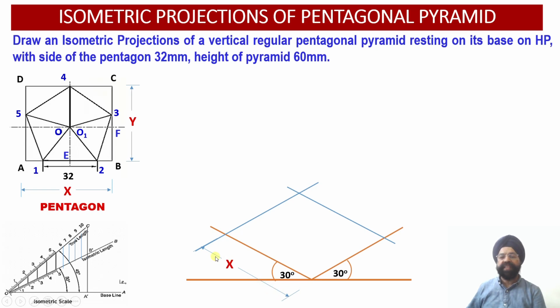By drawing the larger distance of this rectangle ABCD onto the x-axis, we have maintained that we are going to draw these edges, either this edge or this edge. One edge will be drawn on this line and another edge will be drawn on this isometric line, right? First of all, we have marked the x millimeter distance starting from this origin point. So this is the origin point.